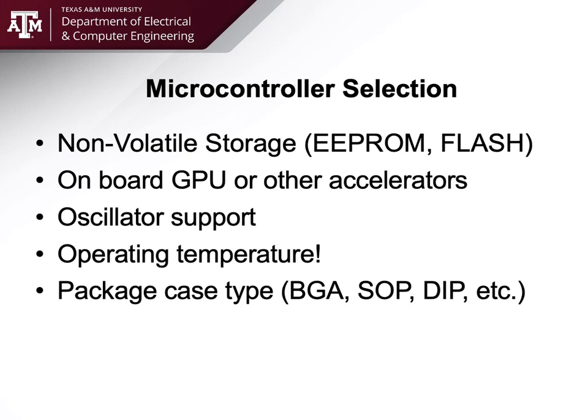Now, if you want to go get a board made with a really high-end processor, instead of buying a single board computer that has one, because guess what, your Raspberry Pi uses a ball grid array. It's soldered professionally by a pick and place machine. If you want to use a ball grid array, I'm not going to force you and stop you. I'm going to give you the advice not to do it.